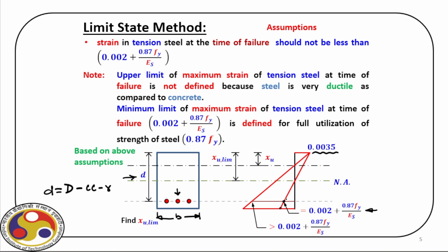Now we can extend this line and we can also find out the strain at the extreme fiber, but because we do not consider the concrete in the clear cover, we will mostly focus on the strain value on rebars, right? Now we have this triangular diagram that defines a location where we have zero strain somewhere in between. And that is what is called neutral axis.